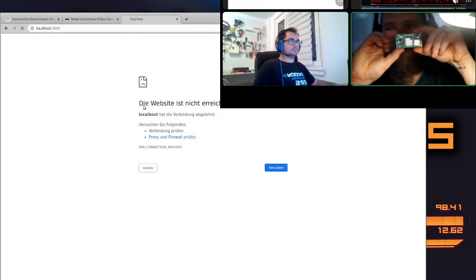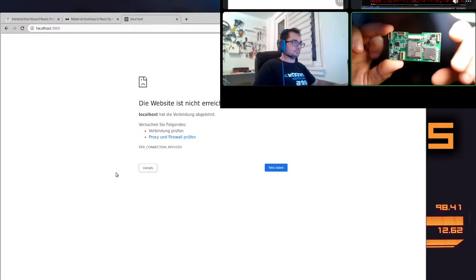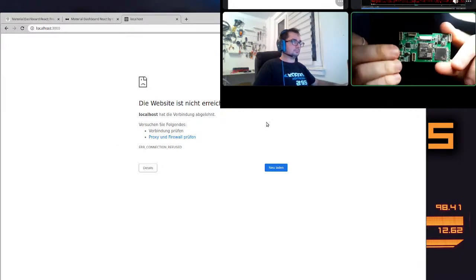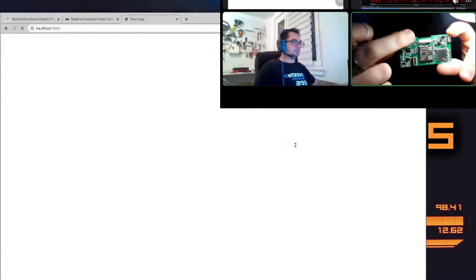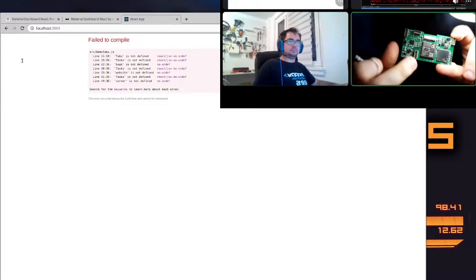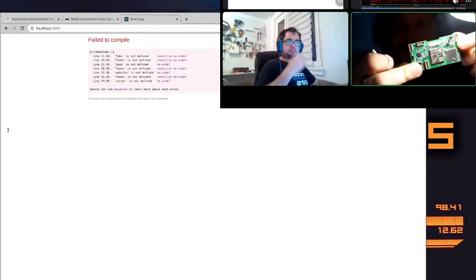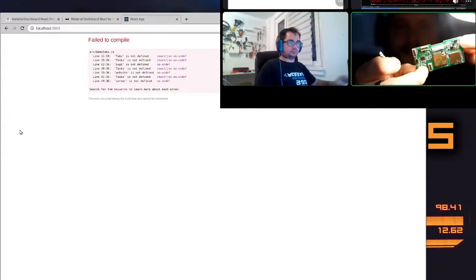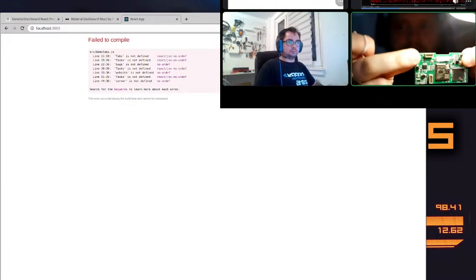Yeah, so I think that's the closest I can get. Yeah, so that's how the PCB looks like. There's the ESP32, that's the key slot. A few connectors, which, well, that's the I2C interface that you can put whatever you want to, and the one for analog sensors. The power one: there's the power, ground, CAN and K-line. So you connect this to your car mostly, and the rest you connect to different things.